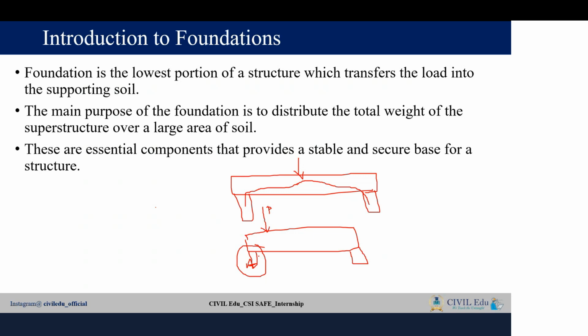Now, when huge amounts of stresses are coming to the support, what will happen? Till it reaches the limit state, it is fine and it will be carrying the load. But once the limit state gets crossed, cracks will get initiated in the structural element. Once the cracks get initiated, over a period of time the structure fails. That is what happens when the load distribution doesn't happen evenly. So the purpose of constructing foundations is to distribute the loads evenly.